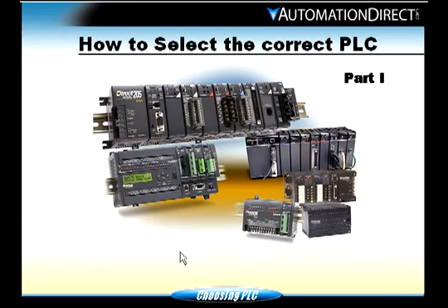Okay, first thing, as you see here, we've got some nice graphics of the PLCs that Automation Direct offers. The first is a brick unit, which is the 05. I'm pointing down at the bottom. It has an expandable slot, and we'll go into that a little more later on. The next one is a 105, which has no expansion and has one communication port, but it has an option that people like, which is a built-in DC power supply.